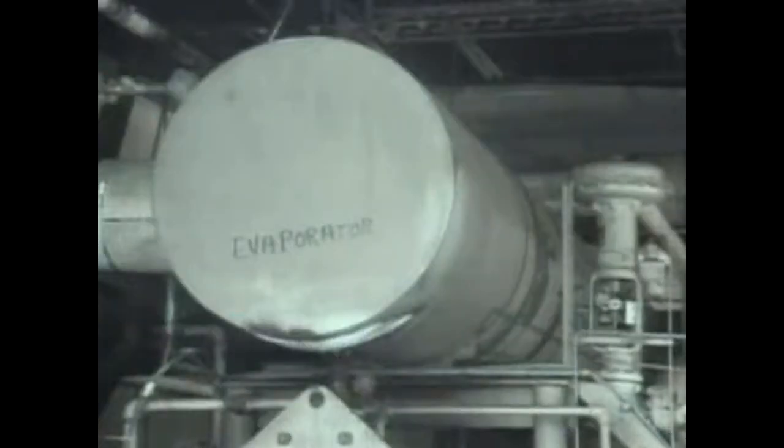A similar problem is low refrigerant flow. One place where this is a problem is in the evaporator. When refrigerant flow through the evaporator is too low, less heat will be removed from the substance being cooled. This will cause the temperature of the substance being cooled to increase.